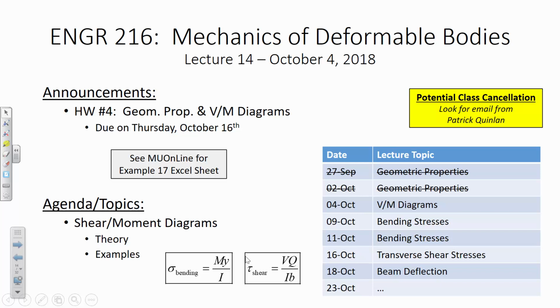But you also need to know the distribution of loads on the structure, namely the moments and then also the shears, okay? And so these stress formulas take a little while to properly derive. So you have to take a step off to the side and talk a little bit about, let's say, the geometric properties. And now we have to take another step to the side today and talk about shear and moment. So once we've discussed geometric properties and shear and moment diagrams, then we can get back into the swing of things with stresses.